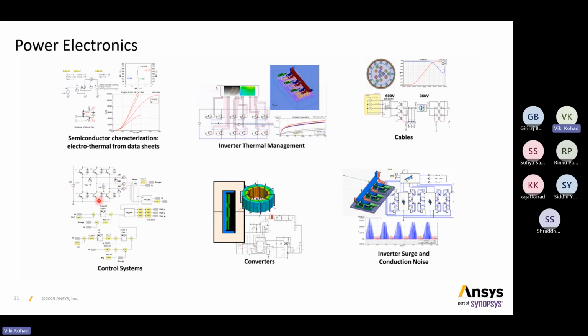How actually you can control your motor or your device. If an electric vehicle is there, you have to control your motor. You have to draw the current from the battery and provide the current to the motor. So first the inverter or your control system draws the current from the battery. Then based on the input values you give to the controller, if you press the brake pedal, it gives the signal to reduce the current value so that the motor RPM gets reduced. That is the control strategy. If you press the acceleration pedal, then the current value needs to be increased by the battery. Then a higher amount of current needs to be provided to the motor section to increase the RPM. That type of control strategy you have to develop inside Simplorer.